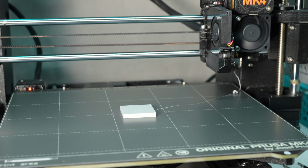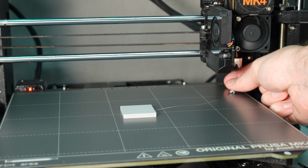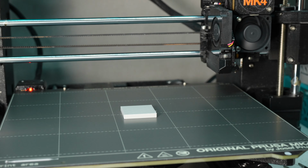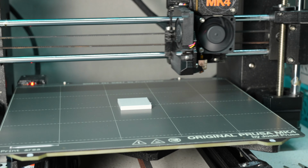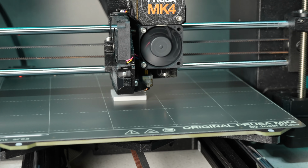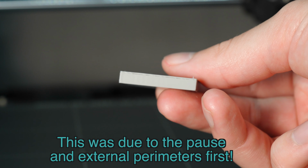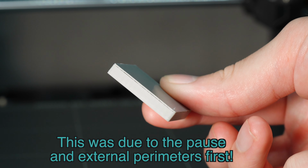If you did something like a pause print and the tool head had to move away, stop extruding filament, and then start again, when it starts it might not be perfect. So I do recommend to use like a prime tower or print another model or something, just so it can start extruding and then go to the model that you want to look good and do your outer perimeter.